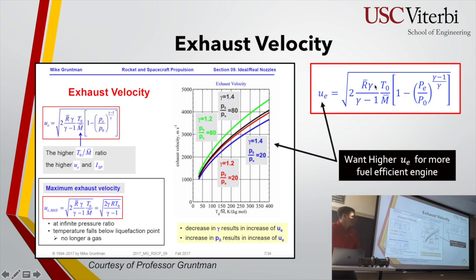And it equals this sort of stuff. You have your R, which is the universal gas constant here, so that's just the same number. Your gamma is what NASA CEA told you, and that has to do with your O/F ratio, right? If you have more of something that's lighter, that has to do with your combustion. And then this is pretty much the main thing that dictates a lot of things: T naught over M bar.